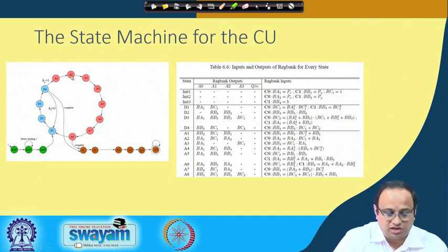And the addition is done conditionally in this architecture. Later on we will see that this is not a very secure way of implementing things, but at least from a performance point of view this looks fine. Then there is a final step of inversion, where you bring the result back from the projective to the affine coordinates. This is shown here in the brown line, and it turns out to be 24 clock cycles when employing the Ito-Tsujii inversion algorithm as we have studied previously. So here is a snapshot of the control logic.